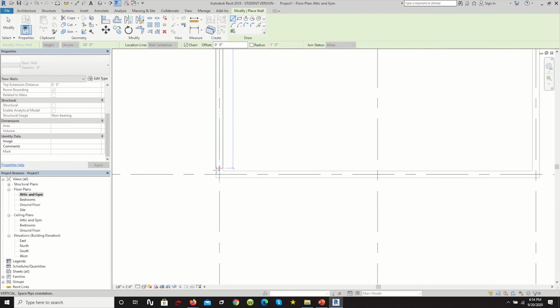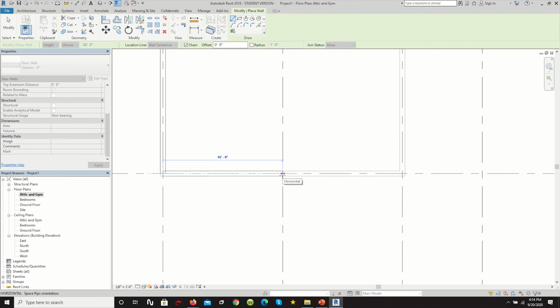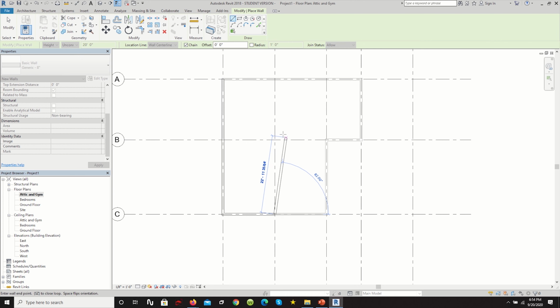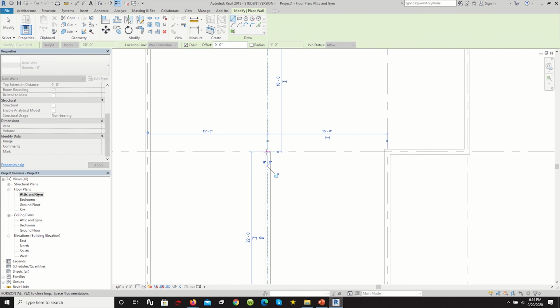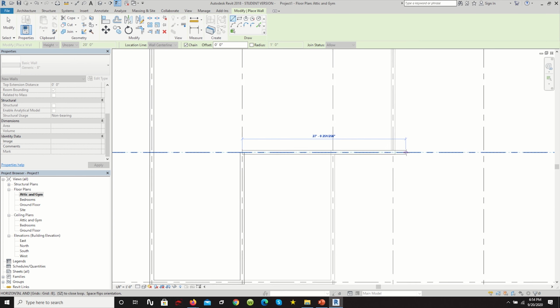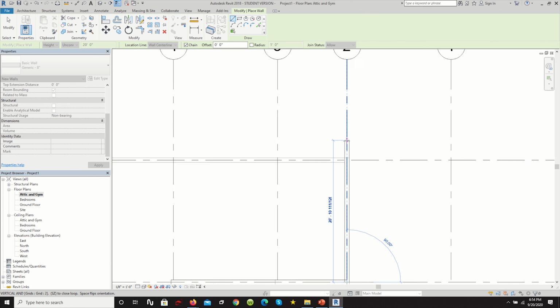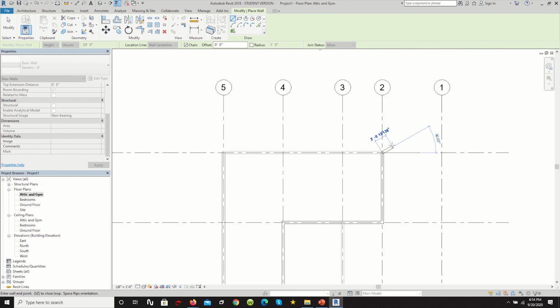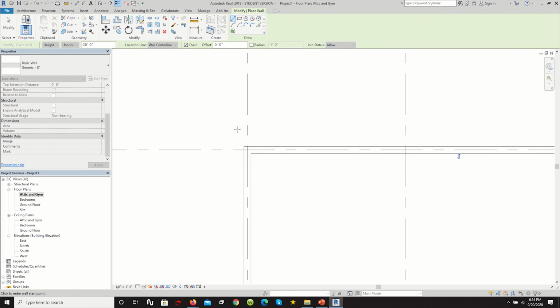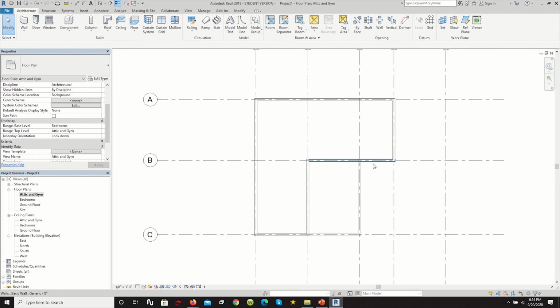Let's begin drawing here. We want it to be about halfway, which is about 15 feet. And then we want it to intersect with this part of the grid line. So this is why your structural lines are so important, because now it's serving as a reference point for me to draw the third level. And then we'll close it right here. And this will be our third level.